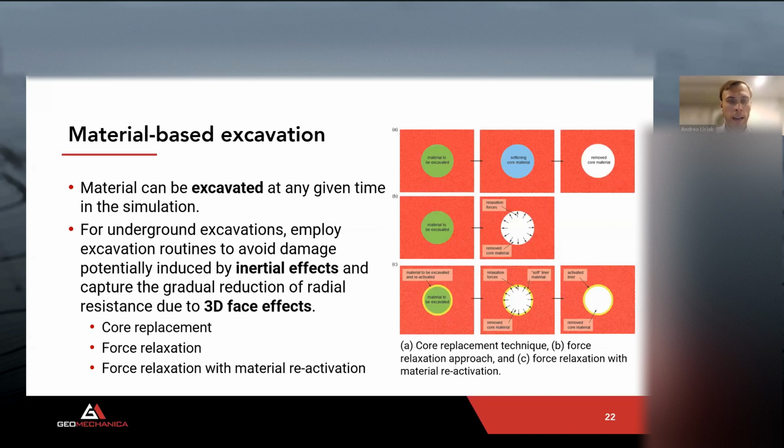Another feature recently added or improved in the latest version concerns material-based excavation. If you are to model an excavation, you'll probably be using this feature. In Irazu, you can excavate a material at any time during your simulation. But what is important in underground excavation is that there needs to be a routine to avoid the damage that can be induced by the removal of the material due to inertial effects. Also, when you model an excavation in 2D, let's say a tunnel excavation, you need to be able to capture the gradual reduction of radial resistance inside the tunnel due to the 3D face effects.